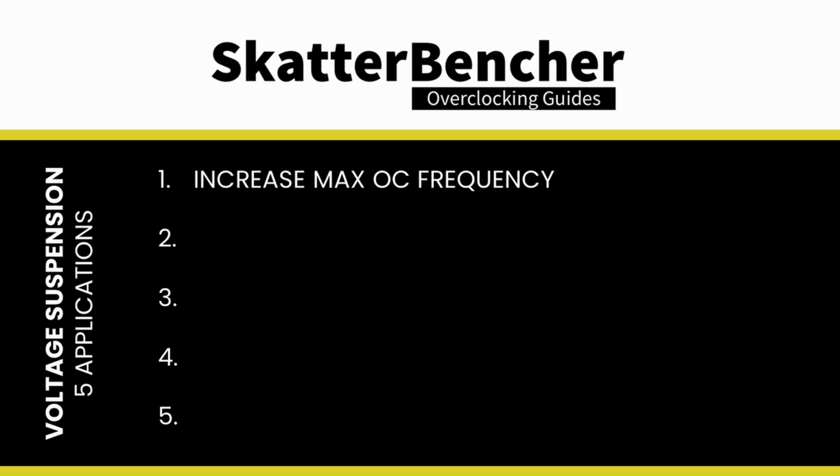This may help you stabilize the overclock. Second, you can achieve slightly higher peak effective clock frequencies for light workloads by trimming the maximum voltage using the voltage ceiling. The starting point would be to check the peak voltage first, then lower it step by step using the dynamic ceiling Vmax.